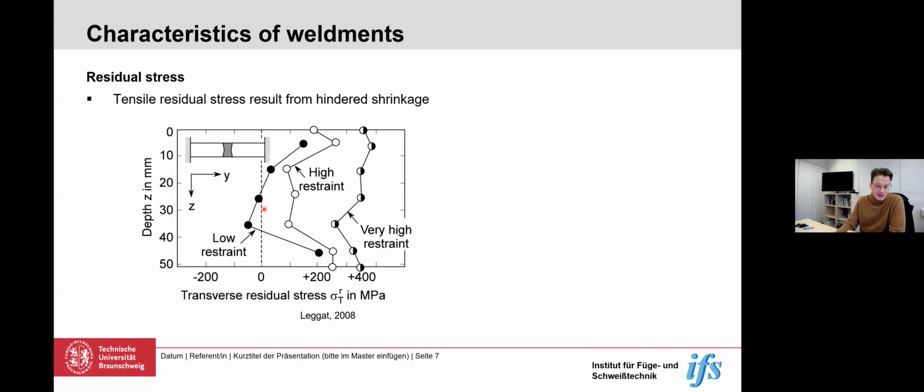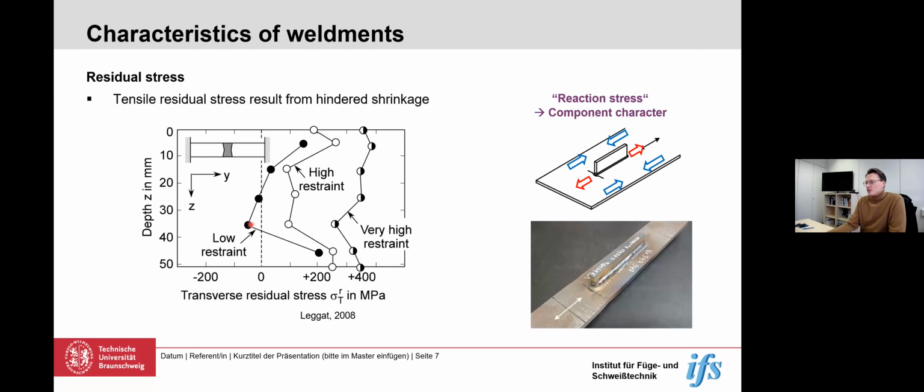And of course, if investigating residual stress effects in the laboratory, usually the problem is that you have low restraint, because we weld small scale specimens with low restraint perpendicular to the weld, and the result is low residual stress. When investigating residual stress effects, having low residual stress is, of course, difficult. So what you need, when you are interested in investigating residual stress effects in high strength steels, is a specimen that has component character, although it is small enough to be tested in conventional test equipment.